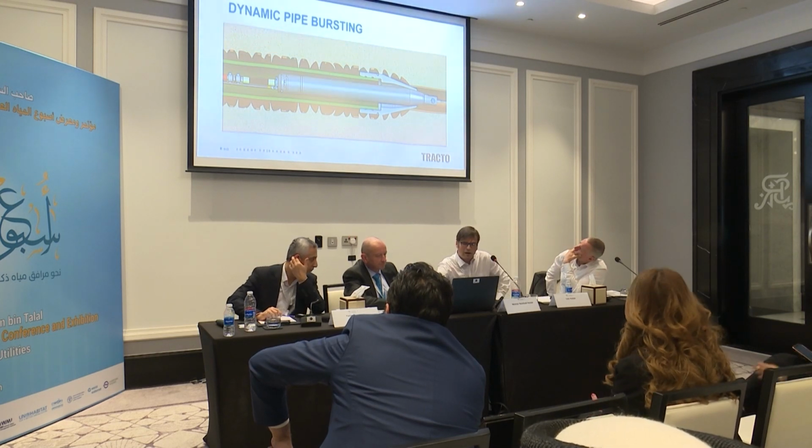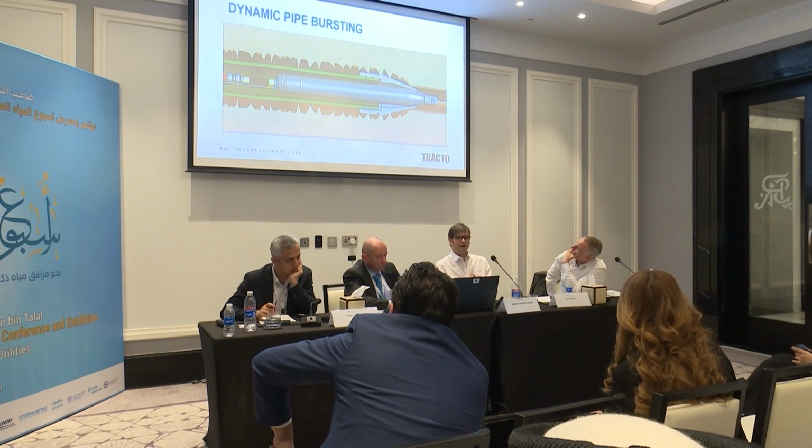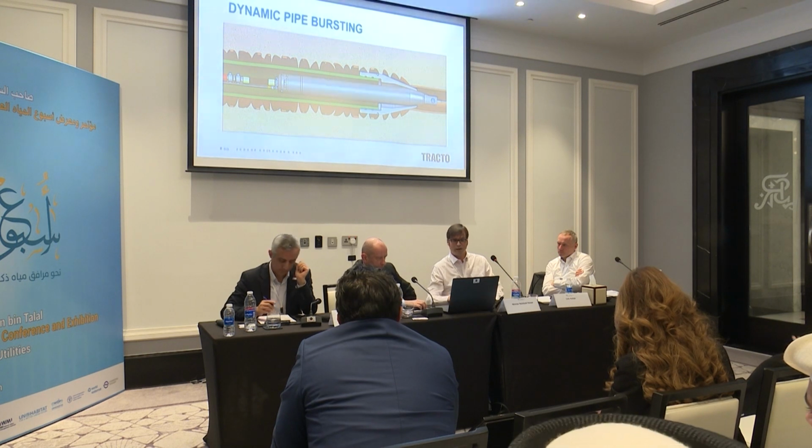you've got a limited amount of materials that you can burst, and most importantly, the pneumatic hammer inside requires pressure air and requires lubrication, and it exhausts compressed air alongside a very, very fine oil mist. So in clean water pipes, this is problematic. In fact, in Europe it's not allowed for clean water pipes. It is something that is often used in wastewater, in sewer pipes.